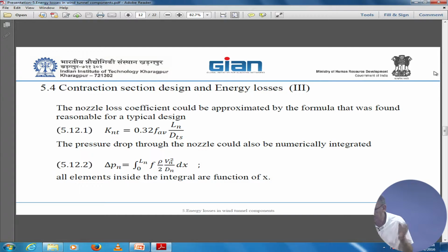A cylinder creates vortex shedding, Karman shedding. You remember? Should we keep more honeycomb structures also? It won't help you. It's a waste, because once you straighten the flow, no argument to put another one. It won't reduce anything. After you straighten the flow, you want to attenuate turbulence level.